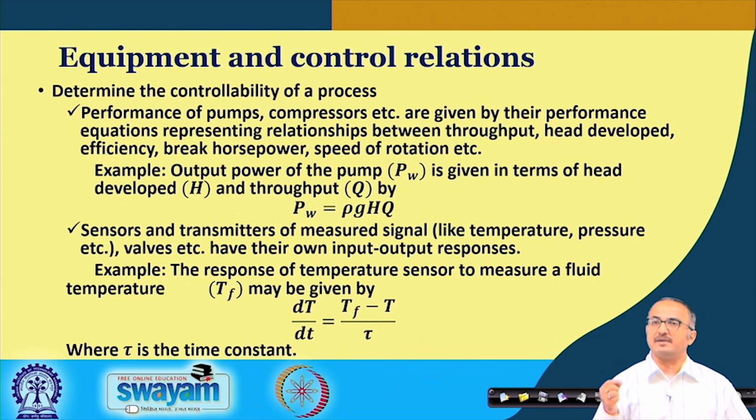This time lag, how fast the change in the valve position will change the flow rate, becomes more pronounced in the bigger scale. You may not feel it in smaller scale, but in a bigger scale, the effect of any change imposed on the valves will be felt on the output side a bit later.